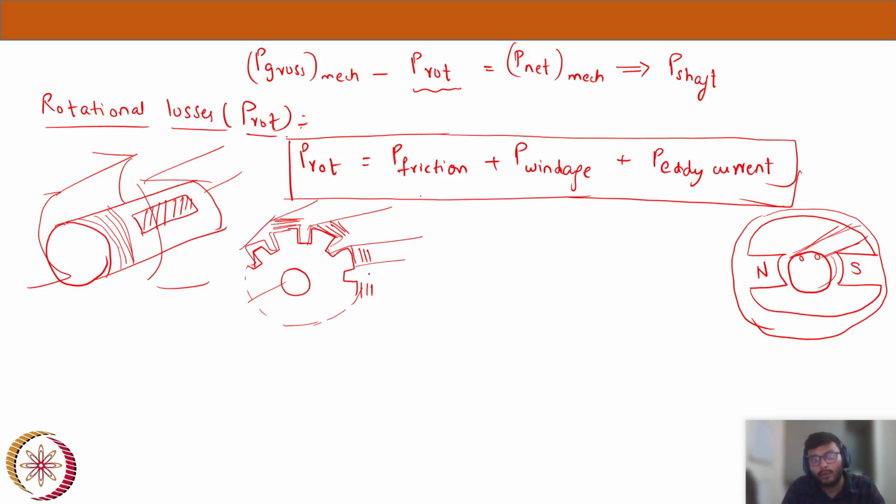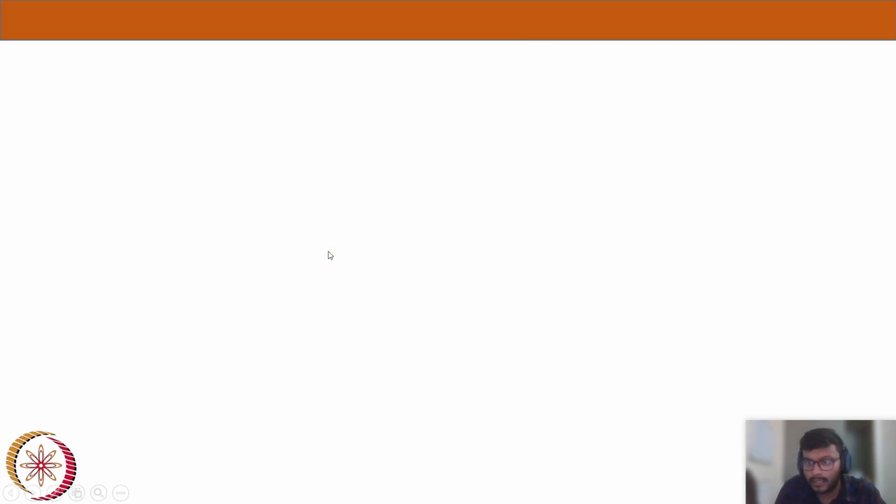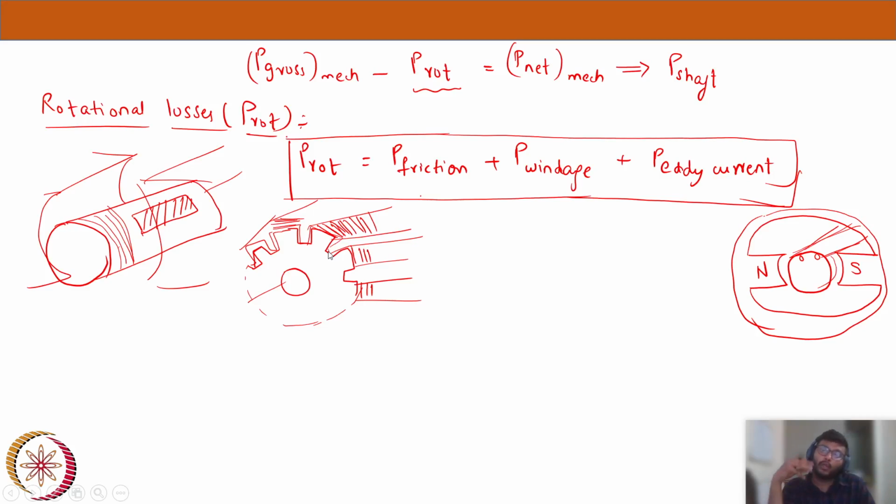Now, what is the use of doing it like this? Here the entire thing is a solid body, but here you are forming a body with single laminations of the rotor. The purpose is that with lamination you are reducing the path for the eddy current to flow. The more the path, the more current will flow, and the more eddy currents there will be. So you are reducing the path and thereby minimizing the eddy current. That's the idea of using laminations in any kind of machine.